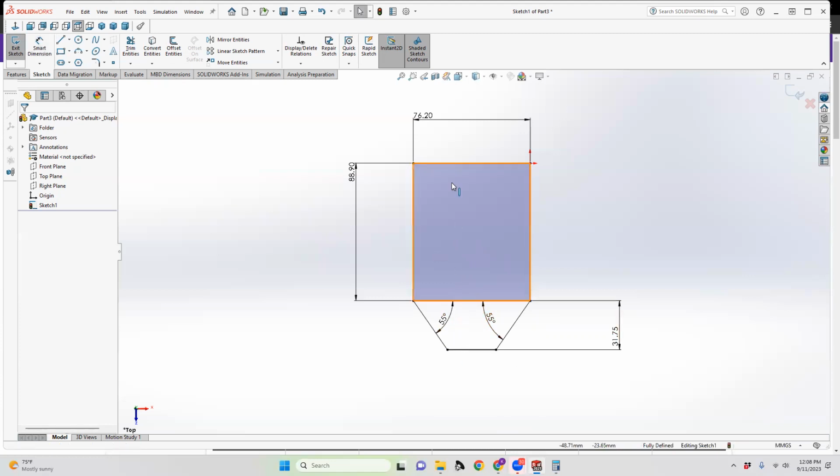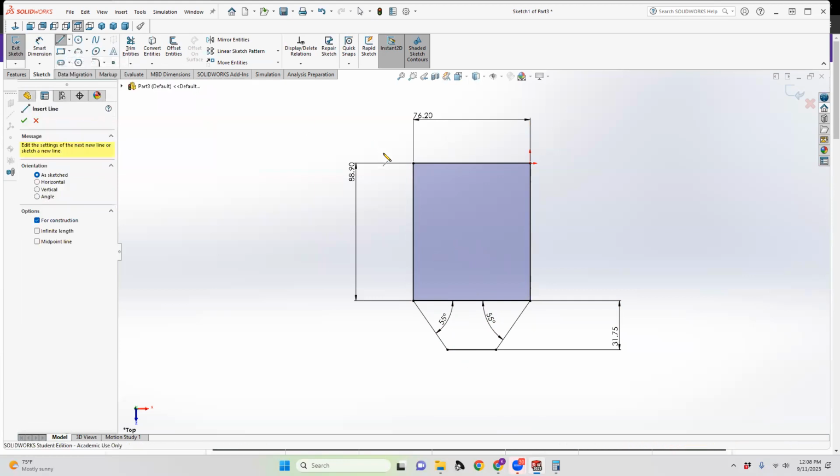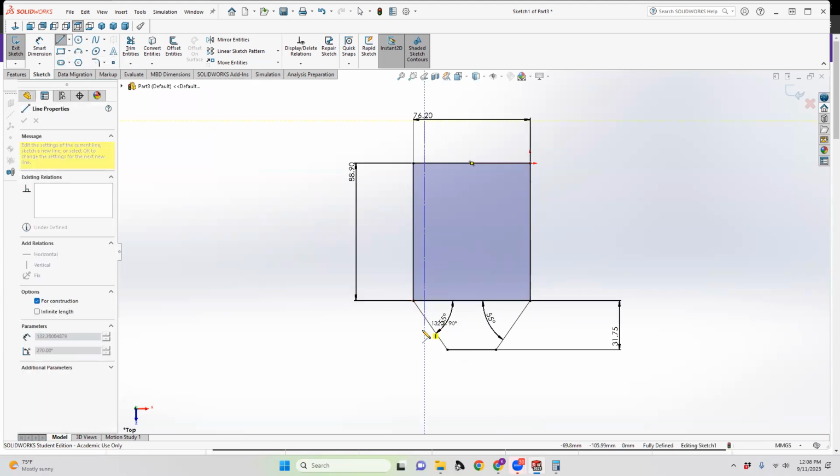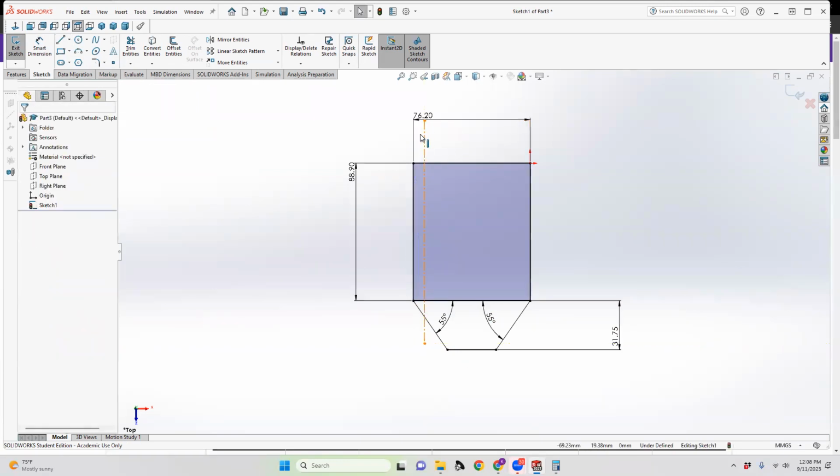What we can do is then start using our pattern, but we're going to need a reference point. So instead of making more lines, we're going to use center lines. So what center lines do is they give us the ability to do some pretty cool things. So in this case, if this is 3 inches wide, then maybe we want about 1/4 inch spacing between center lines. What we can do is a couple cute things.